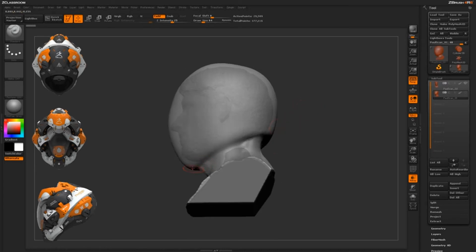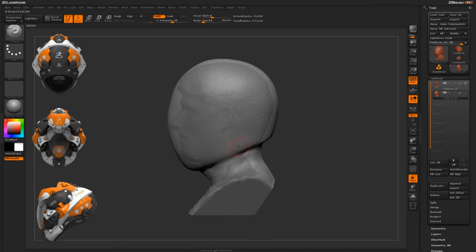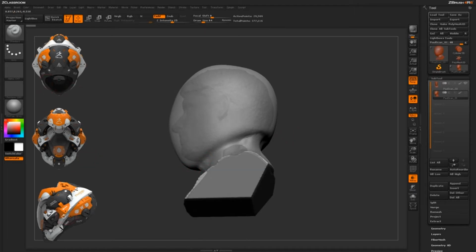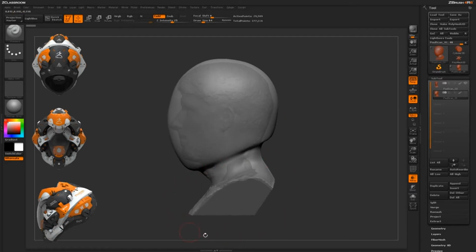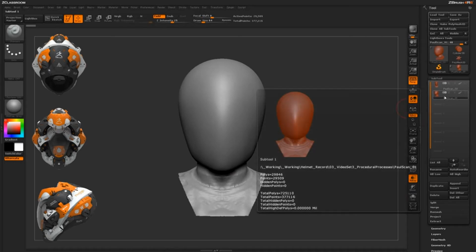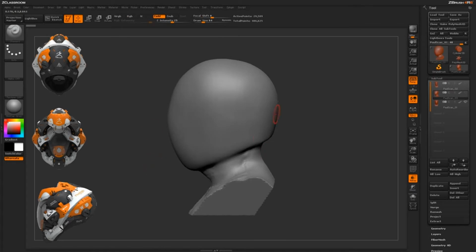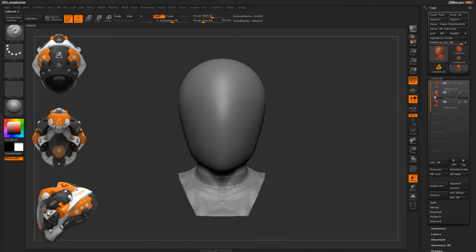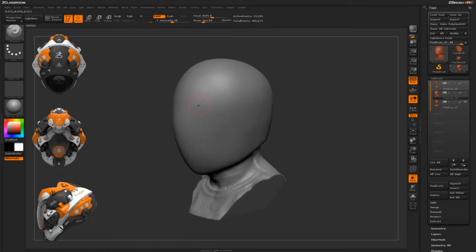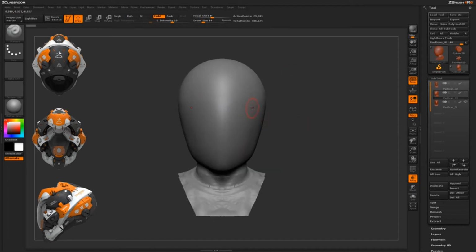Another thing to note is I have this space carved out of the lip of the actual helmet, where it will touch the neck. So I don't really need the base of this model anymore. At this point, I'm going to duplicate this base mesh again, and store it as a duplicate object in case I need to hollow out the helmet afterwards. If I start flushing in a lot of details and they start going through this interior space, I can do a subtraction process and remove the interior again if needed.